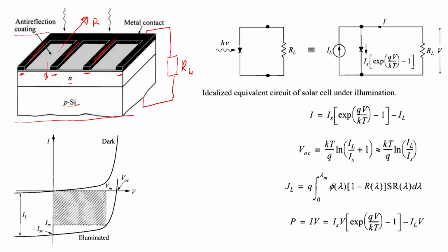So we want to find some compromise between shading of our solar cell and having these metal rods close enough that photogenerated charge carriers can reach them before they recombine, so they are collected by this metal grid and contribute to some current in the external circuit. So that is the general device configuration of a solar cell.